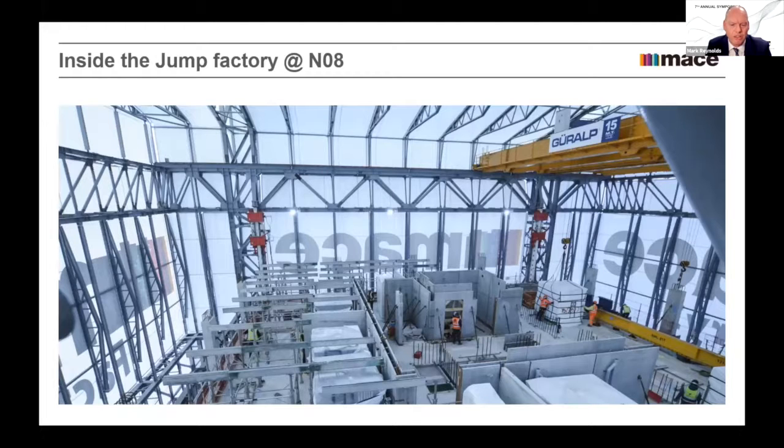We could work on the top deck. The next deck down, we did the cladding. And then the next deck down, we started the floor loading and floor finish. We achieved an output of 1 floor in every 55 hours. That was including walls, floors, columns, pre-assembled risers, service modules, bathroom pods, and utility cupboards. The downside was it cost us £15 million for the 2 big tents. Took us 8 weeks on the critical path to erect it and 4 weeks on the critical path to dismantle it.